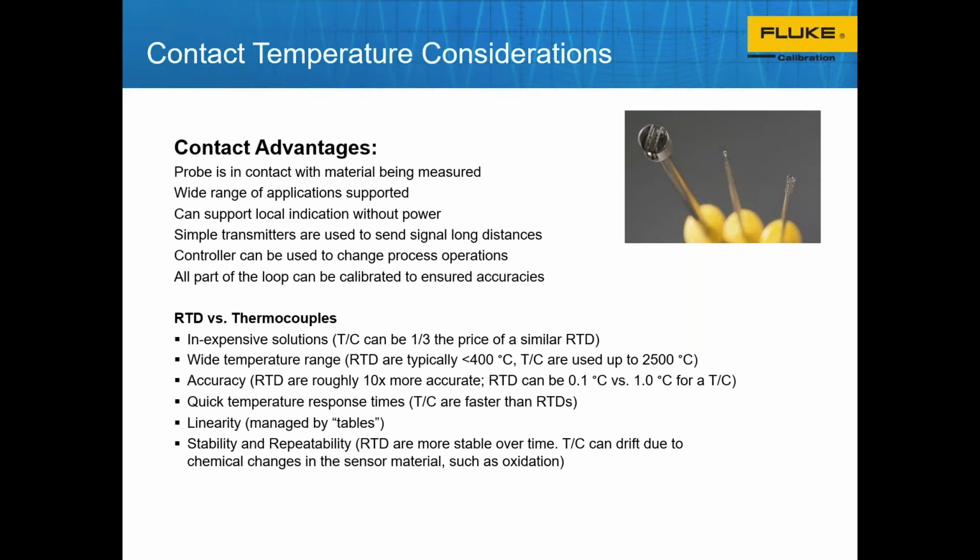The temperature response time on thermocouples is much faster than RTDs. RTDs are resistance temperature devices, and the material itself needs to change temperature, where you have just a single point of temperature changing at the junction on a thermocouple, and it's much faster.